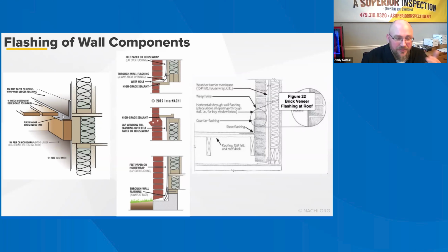But when you have a deck with a roof, they will use the roof as a means to say that it's not required. The deck ledger flashing is not required because it's covered by a roof. Well, the middle part of the flashing is probably protected. The ends, which are the most susceptible to water intrusion, are not protected, especially when you have wind-driven rain events.